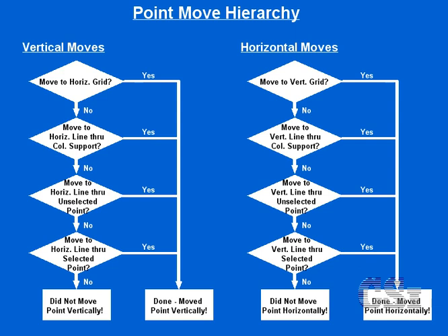Please note that once a point is moved in a specific direction, it will not be moved again in the same direction for any of the conditions that may follow. It is important to also note that when checking against lines through points, it checks the points in the order drawn. From this flowchart, you can see that this command has many conditions to check, which in turn are very order dependent, and thus it is important that you understand this option before using it in any substantial manner. Now let's see how this works in reality.